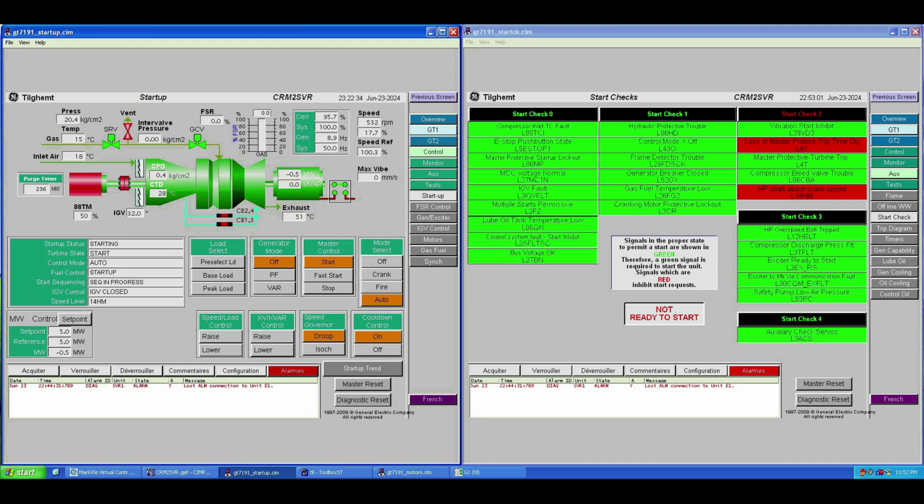Gas-fired units that have exhaust configurations which can trap gas leakage, like boilers, have a purge timer L2TV, which is initiated by the L14HM signal. The purge time is set to allow 3 to 4 air exchanges through the unit to ensure that any combustible mixture has been purged. The starting means will hold speed until L2TV completes its cycle. Units without complex exhaust systems may not have a purge timer and rely on the starting cycle and natural draft for purging.